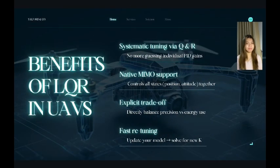This brings us to the main advantages of using LQR in drone control. The first one is systematic tuning. We express our goals in the Q and R matrices instead of manually tweaking 3 or 4 PID gains, and we see immediately how the trade-off shifts. The next one is MIMO capability. A quadcopter has 6 states: X, Y, Z, roll, pitch, yaw, and 4 rotors. LQR handles that multi-input, multi-output problem with a single gain matrix.